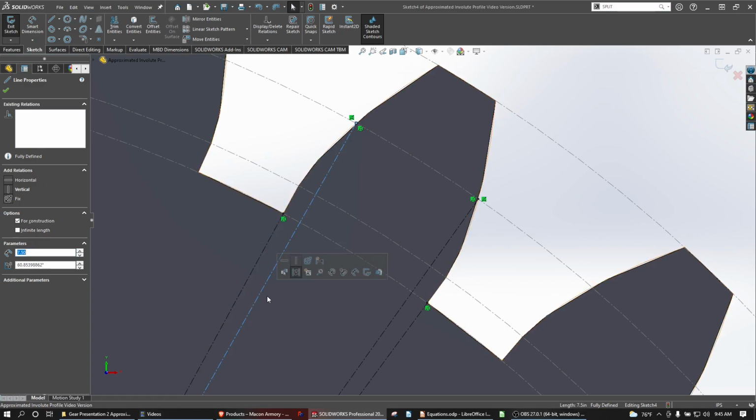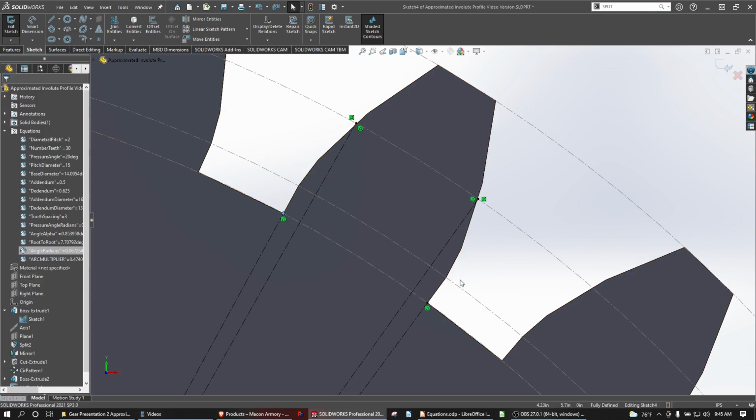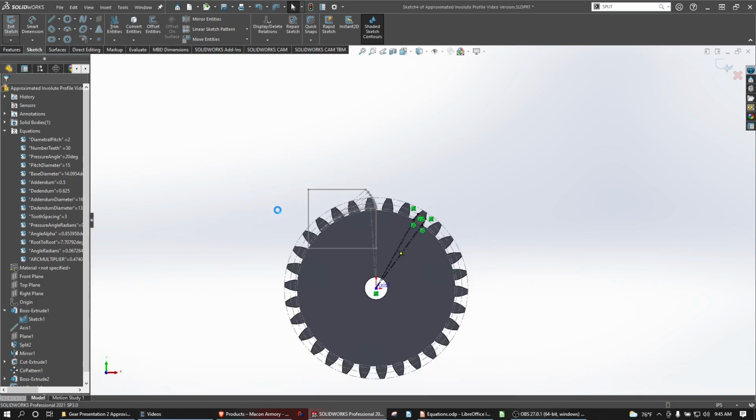And you add that to the first part of the root to root angle equation, that's this angle. So that's how we find the angle of root to root when we go to dimension these teeth. That's what we're figuring out. So this is 360 divided by 2n, and this is the angle alpha. That's a very long equation that we just made. So that is how that works.